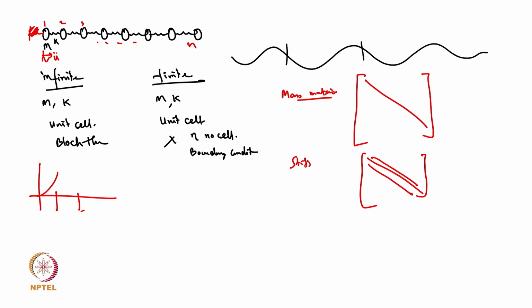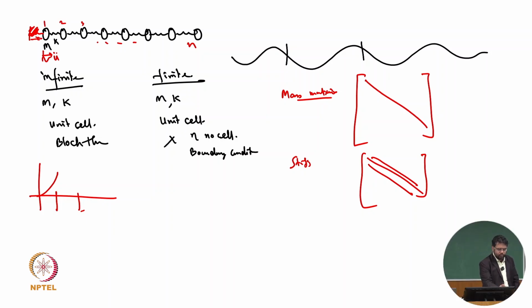We can put a shaker at that portion and excite it, and we can place an accelerometer at that point and measure how much acceleration is coming there. Or maybe we can point an LDV, laser Doppler vibrometer, and measure how much velocity is happening, or we can put a displacement sensor and measure how much displacement is happening. So we can do that type of setup and try to measure how much vibration is going to the end.